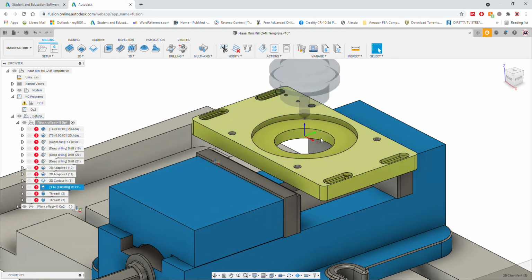Of course now you don't see anything because I didn't select anything. Those are already there for you to then just modify for what you need. So for instance, I put in some thread milling. Let's say it is a part we will need, but we don't have the tool ready, so you don't want it anymore. Perfect, you select it, you remove it, so you just keep what you actually need.